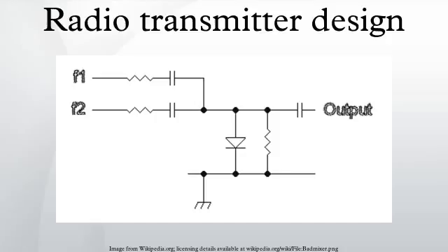The audio input operates the regulator in such a way as to produce the instantaneous anode voltage needed to reproduce the modulation envelope. An advantage of the series regulator is that it can set the anode voltage to any desired value. Thus the power output of the transmitter can be easily adjusted, allowing the use of dynamic carrier control.